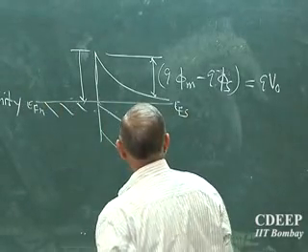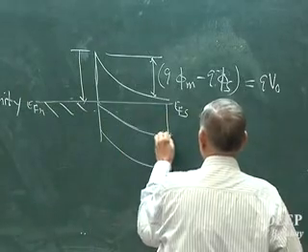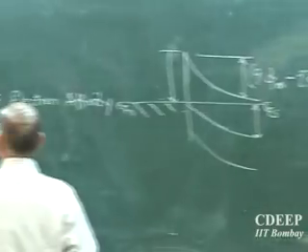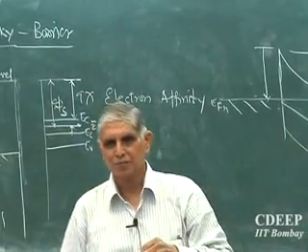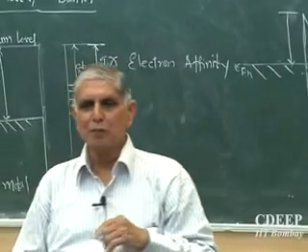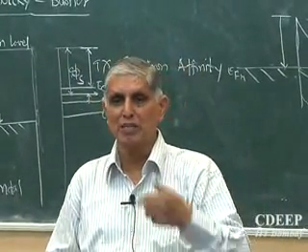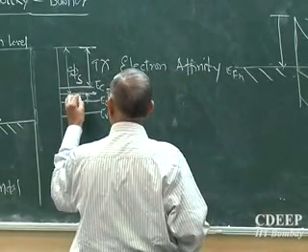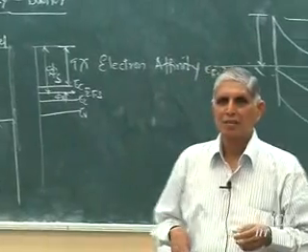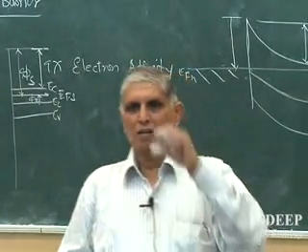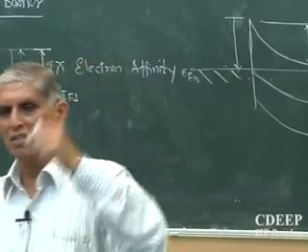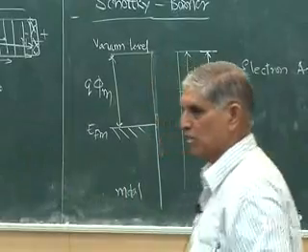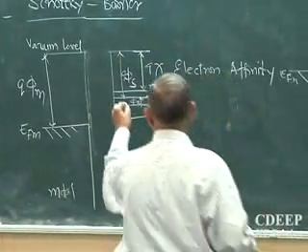Okay, another term you should now know: Fermi level minus EI, EF minus EI. What is this actually? What is it called? Fermi potential. How far you are away from intrinsic is called the Fermi potential or Fermi energy. So this is given the name phi F. Phi F is EF minus EI, or EI minus EF, by q of course, because EF by q is voltage. So maybe you can write q phi F.